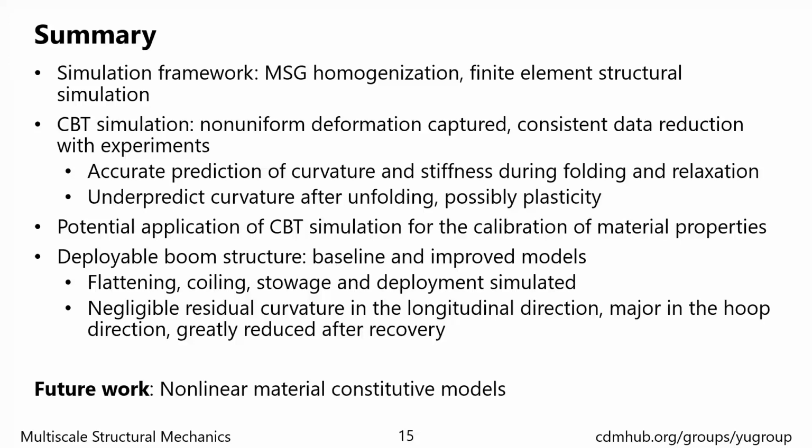We also simulated deployable bone structures, including coiling and deployment. With the baseline and improved models, we found that the residual curvature is negligible in the longitudinal direction, but major in the hoop direction, and it can be greatly reduced after 24 hours of recovery. In the future, we are going to apply some nonlinear material model to the simulation to see the effect on the prediction of residual deformation.